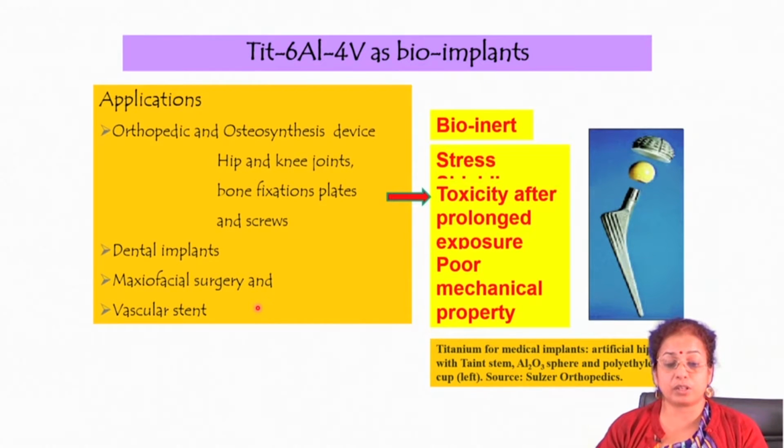usually prior to applying Ti64 as an implant inside the human body, people go for a typical hydroxyapatite coating on the surface by the dip coating technique. But the problem of hydroxyapatite coating by dip coating is that this coating is very fragile in nature. So, its durability decreases to a large extent, and hydroxyapatite gets dissolved gradually, and naturally it reduces the lifetime of the component, particularly when it is a fixed implant.